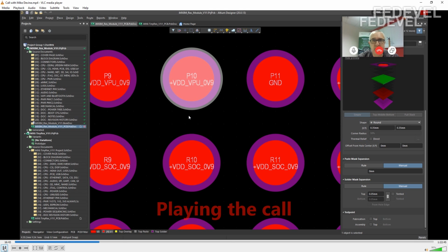The other option, just for exception, others may well have conductive paste. We don't use conductive paste. We prefer just a copper fill. Okay. And can you do copper fill inside of these through hole vias? Yes. And they will be completely filled with copper? They're completely filled with copper, yes.